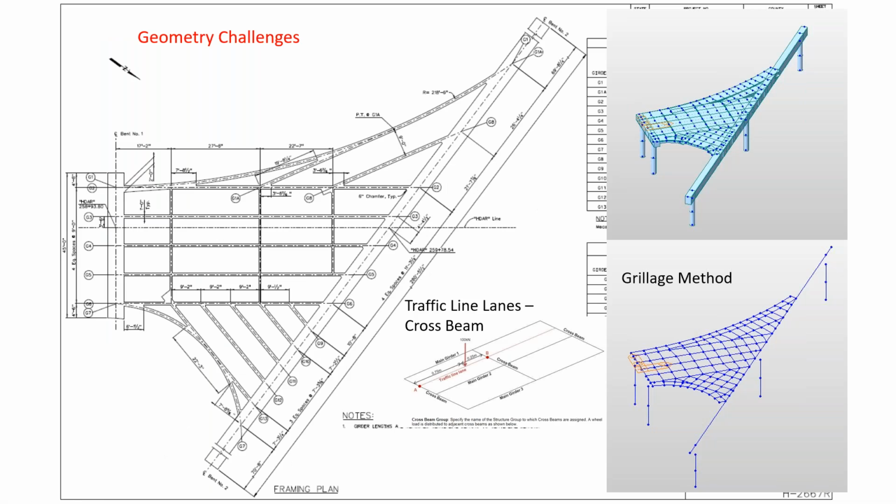Here you can see the layout of the framing. You can see all the girders that are taking the flares. There is this girder that I am pointing to with my mouse. Girder A has a post tensioning that is inside the cell of the box. Similar situation, girder 13, there is a post tension block inside the cell. Later on, we had some problems pre-stressing this girder and this girder. All the post tensioning was said to be stressed from bend 2, which is where I am pointing with the mouse.